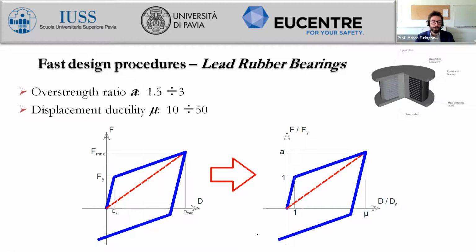But before considering the steps for designing, we have to consider the overall behavior. As I mentioned just a few seconds ago, we can consider the elastoplastic behavior with hysteresis, obviously, for the force response of such isolators. But in order to come up with the fastest design procedure with very few steps and some statistical analysis, I had to switch from the general definition of elastoplastic behavior to this actual diagram, which has exactly the same meaning.